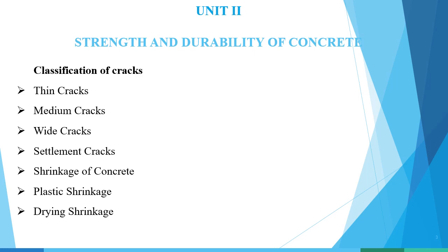It is maintained that more than 50% of shrinkage will have taken place in about 35 days, and a considerable amount of shrinkage will have taken place near the surface even earlier. At such an early age, the concrete will not have attained good strength to resist shrinkage stress, and therefore the concrete is much more vulnerable to cracking in spite of stress relaxation by high creep at low strength.